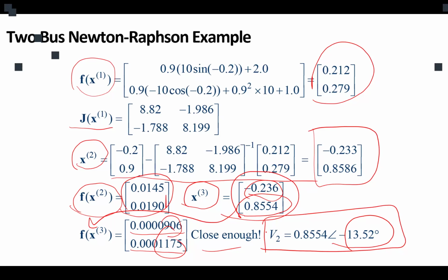And we learn how the Newton-Raphson method, which is the most simple, basic, iterative numerical solution method, works, and how we could use it to efficiently and quickly reach the accurate solution. We ran an example of one simple grid to see how this works and how we could do such an analysis for power flow analysis.